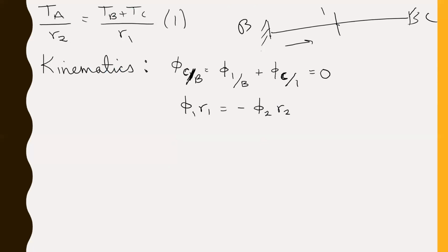But what I recommend is you position yourself far off in the positive X direction or Z direction, whichever direction is your axial direction. So you place yourself far off in the positive direction, which I'm going to say is over here somewhere past C. Then you look back on the object and you always calculate the nearer point relative to the far point. That way you have some kind of visualization of whether you imagine it being clockwise or counterclockwise, and you're always being consistent.